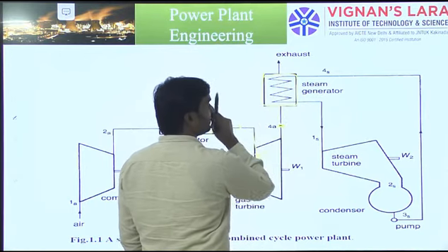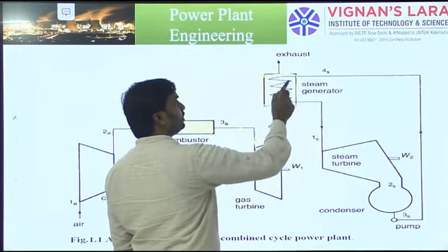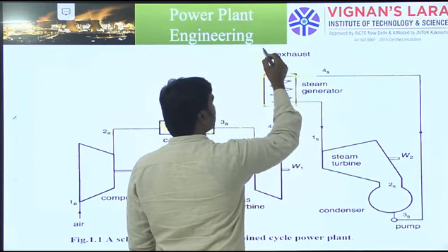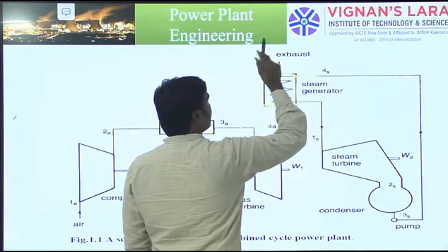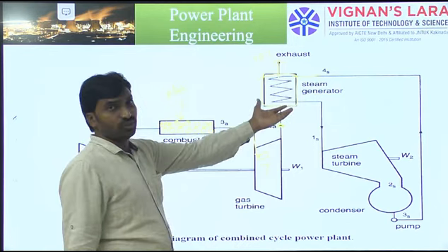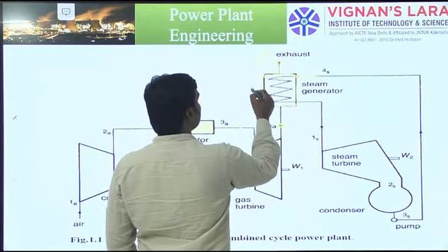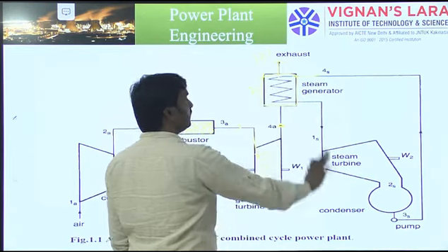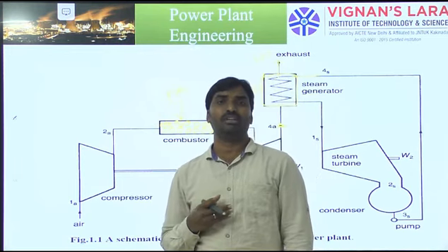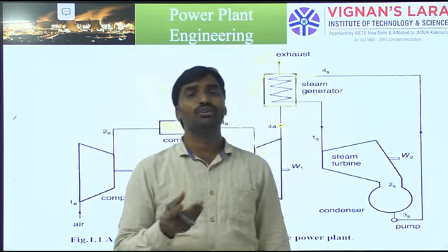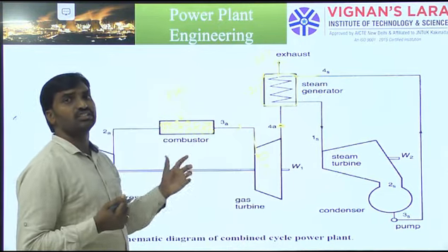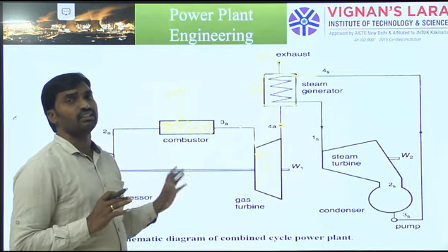Here we need to supply the water and that is converted into steam, and the excess exhaust gases are released. As per our energy discussion, about 10% of the energy is eliminated from the exhaust point, and here 21% of the energy is utilized. It's a rough calculation, not exact. If you want to improve the efficiency, you can consider several parameters: atmospheric conditions, the fuel you are using, the condition of the compressor and the fuel injectors. Everything affects the efficiency of the entire system.